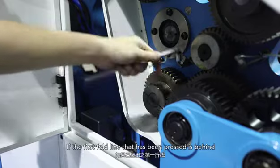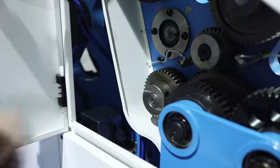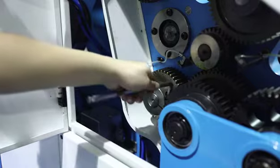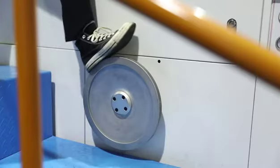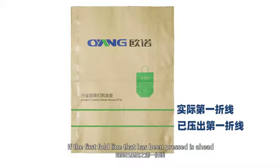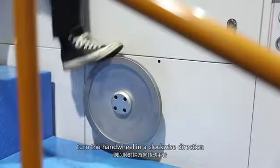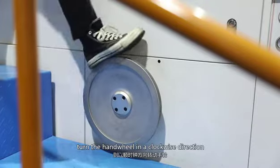If the first fold line that has been pressed is behind the correction position of the first fold line, turn the hand wheel counterclockwise. If the first fold line that has been pressed is ahead of the correction position of the first fold line, turn the hand wheel in a clockwise direction.